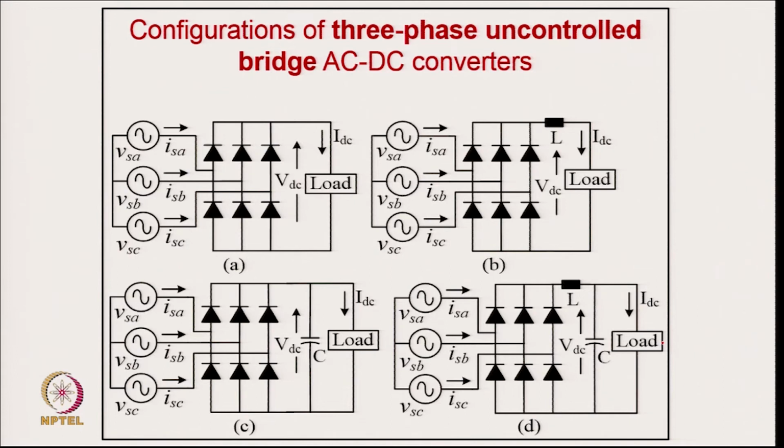And this is the bridge; normally we use the bridge with a simple load, or with a highly inductive load, or we put a capacitive filter. In all the variable frequency type you will find this kind of capacitive filter. So, it will draw very peaky current, and the THD of the current is normally around 60 to 65%. But if you put an inductor with this, the THD can be reduced to around 30%, but this is still quite high because the standard allows hardly 5% total harmonic distortion.